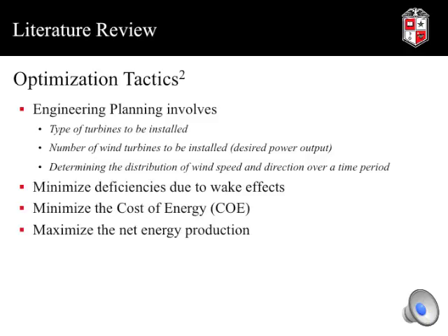An article in the journal Renewable Energy by Gonzalez et al., entitled Optimization of Wind Farm Turbines Layout Using an Evolutive Algorithm, explains that when two turbines are placed too close to each other in the dominant wind direction, the total amount of generated power is less than the initially expected individual power sum, because the wind power in the airstream available for the downwind turbine is now reduced by the upwind turbine.